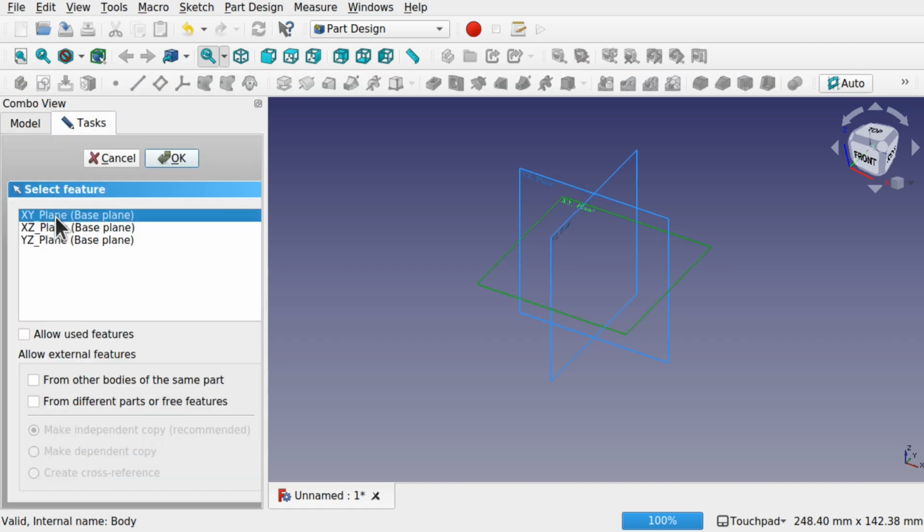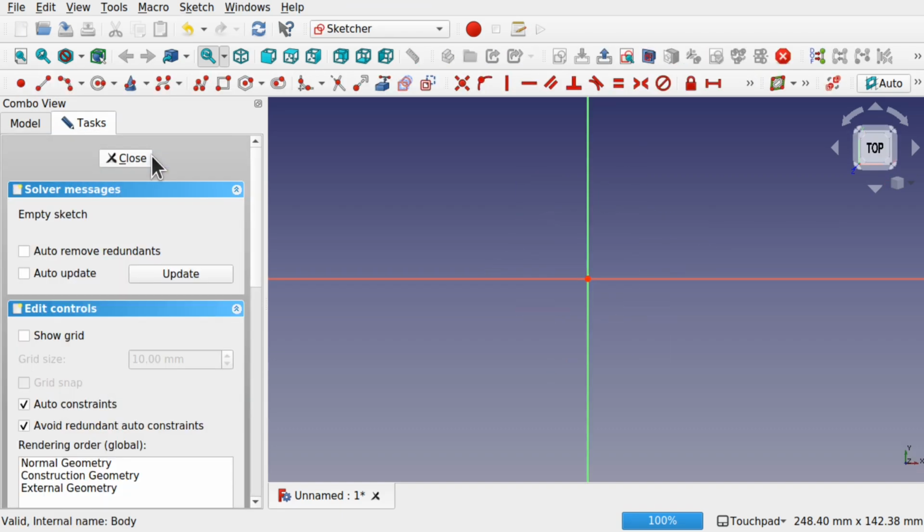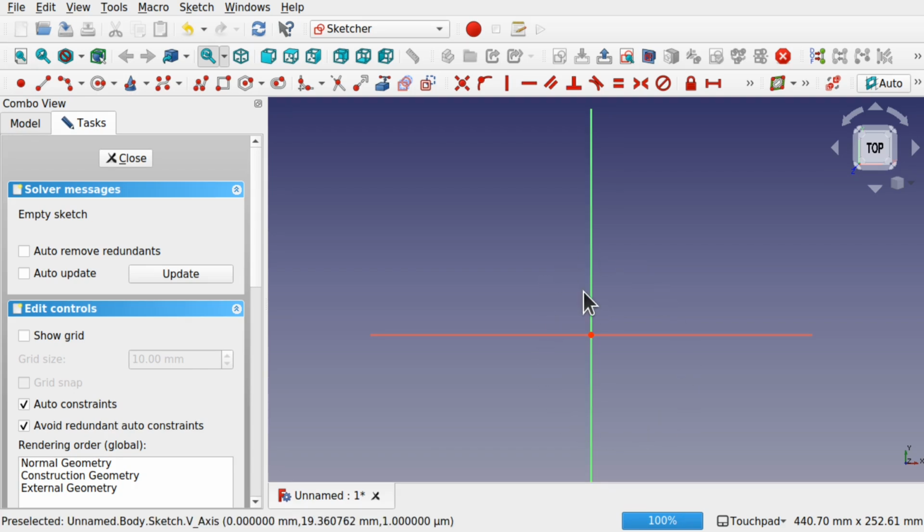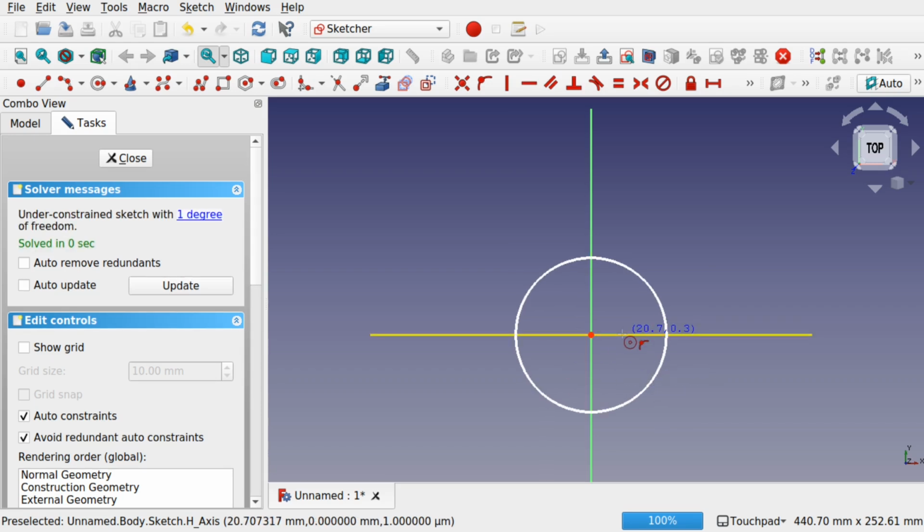And we're looking down, so we're looking at the XY plane. You can see we've got all the geometry coming up here. So we're looking at what we can use to create this object. If we look at the center, we can see basically we can fit a circle in there that we can attach the arcs to. So let's place a circle in there. And also we've got a hole going through the middle, so that will be a circle.